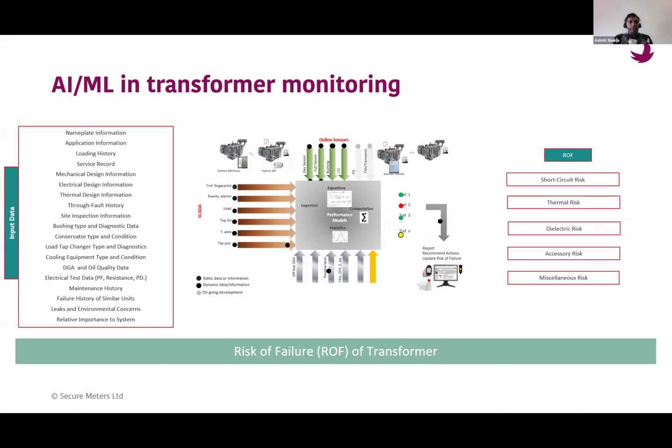But if I know how long it's going to run, and there are different mathematical models available. For example, I think for the transformer there's an IEEE model you can use. So if you have your current, voltage and other parameters, you should be able to predict the life of the transformer. In the same way, as an engineering community, we are academics, so if you can develop a good model to predict the remaining life for this predictive maintenance practice, that will be a really good thing.